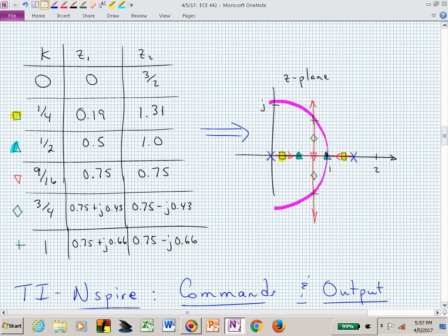So what was the gain k to get us to z equal to 1? In this diagram, that tells us our lower limit on stability. In this case, we would say, oh, to get to 1, we needed a gain k of 1/2. So we need to crank up the gain k at least to 1/2 to get us to the point of being stable. Is that clear?